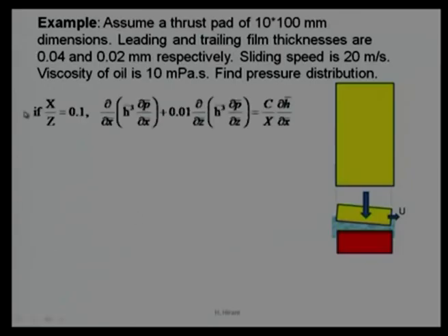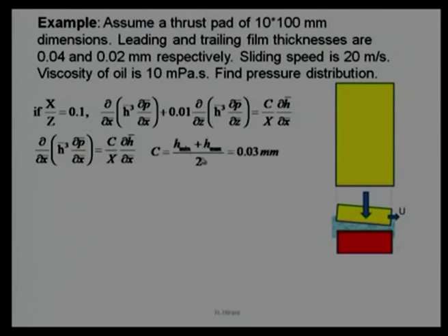To do that, again we can take a few steps, there will be some repetition of steps. In this case, the z derivative term is 0.1, that means this term is negligible, and we are getting only this term. Further, we know the clearance, that is turning out to be 30 micron, and we can express h in terms of x, which was done in the earlier case also.